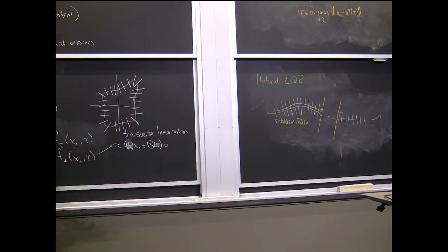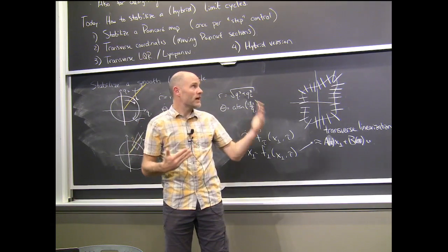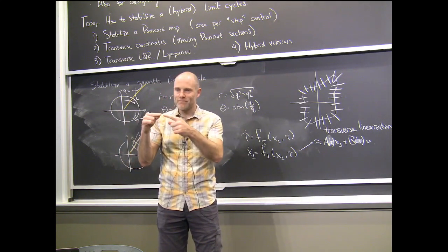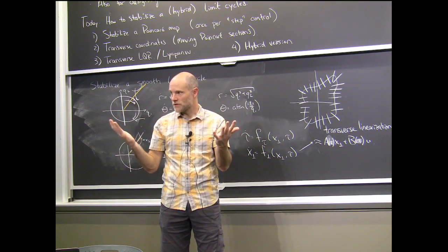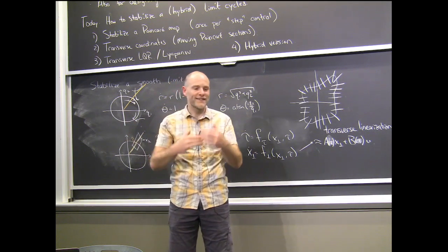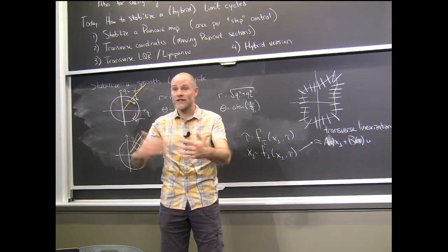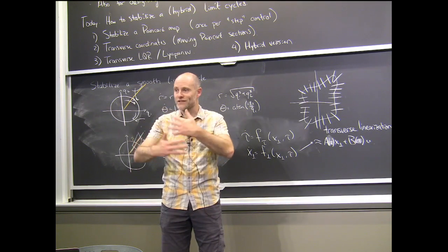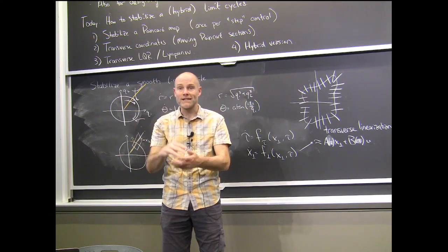Okay, so let me just say again what I said at the beginning, and I promised to say at the end, which is that I think the math of hybrid guards and having a different hybrid mode for every possible contact pair and sticking and slipping and all this will blow up in bigger problems. But really, if you ask even a big system, in your RL controller or whatever, that is capable of being stable on a limit cycle, but you ask it to stabilize itself in time, for instance, you're going to get much worse gains. No matter how you model contact, right?